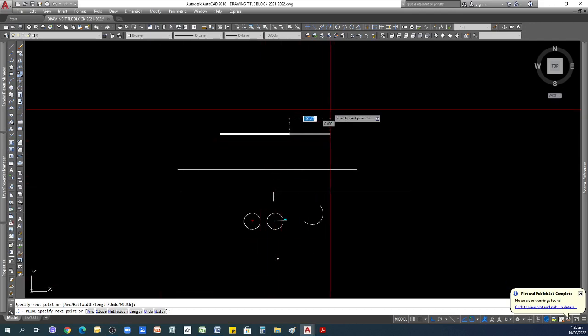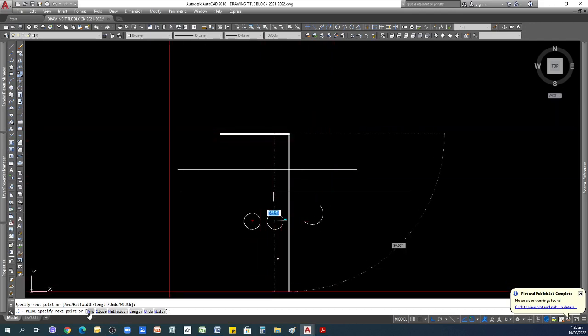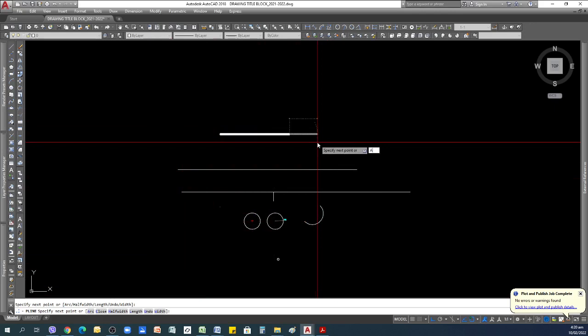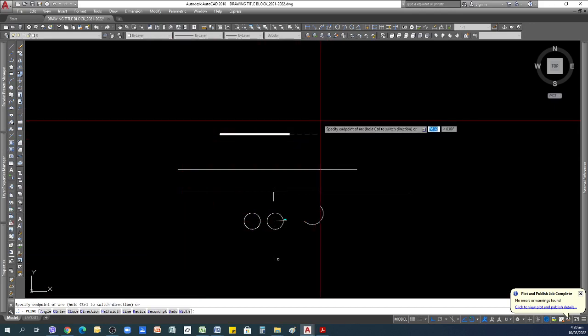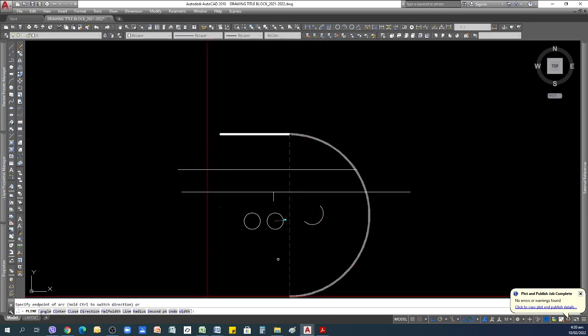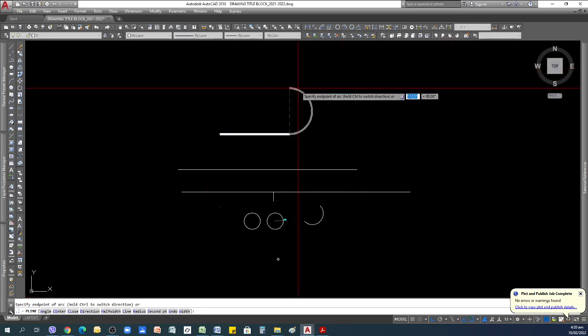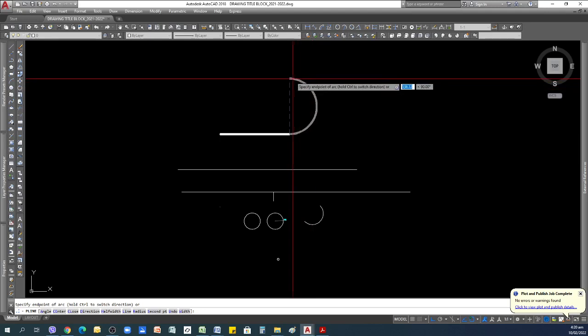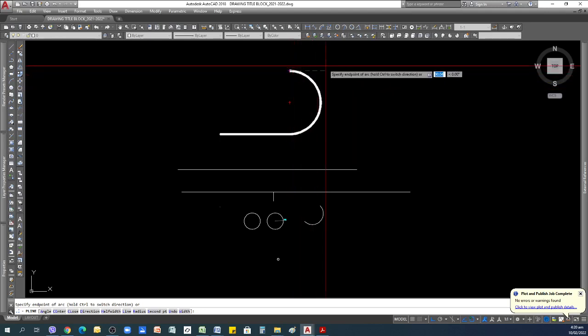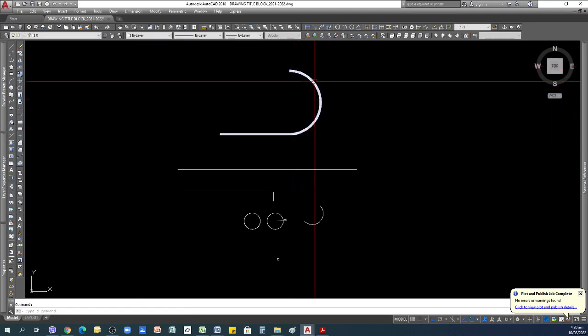And then if I want to make an arc, I will type A, and see, if you do the arc, there are a lot of options here wherein you can enter angle, center, close, direction, halfway, radius. So if you have specific details for this, you can enter them. But just for demonstration, I can click anywhere. So it already creates an arc.